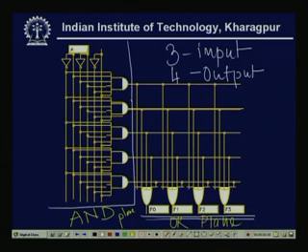Then, as all minterms or product terms are available, any combination in the OR plane can be realized from these possible product terms, and I can realize any 4 outputs from all possible 3-input product terms. So, this is a totally variable structure.